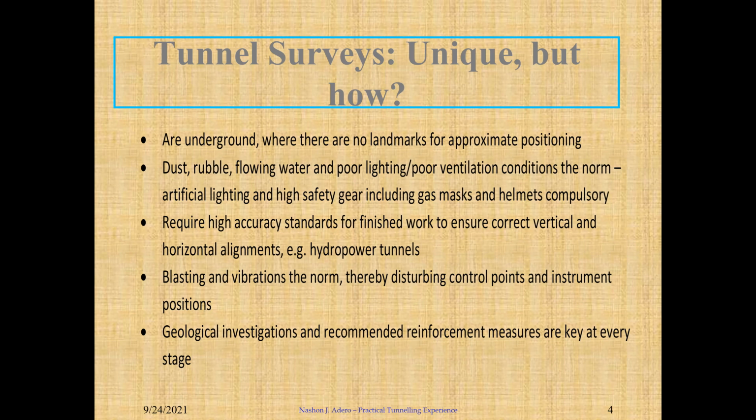So the control points that you've set inside the tunnel have to be checked regularly to ensure that they have not moved, and to tie them to the control points on the surface. So we used to run traverses regularly from the tunnel to the surface, to ensure that the control points were still reliable enough for controlling the work underground. Again, because the tunnel is long, you won't always be able to run a traverse to the surface from wherever you are once you have excavated a long section.